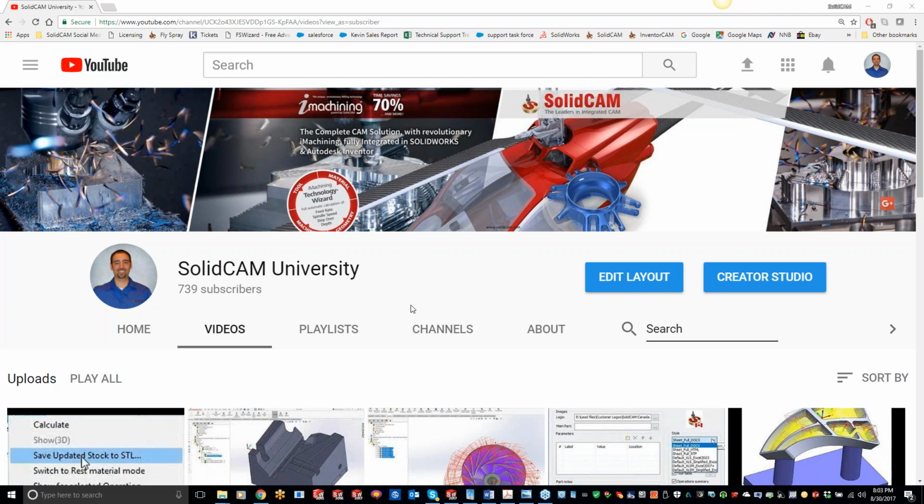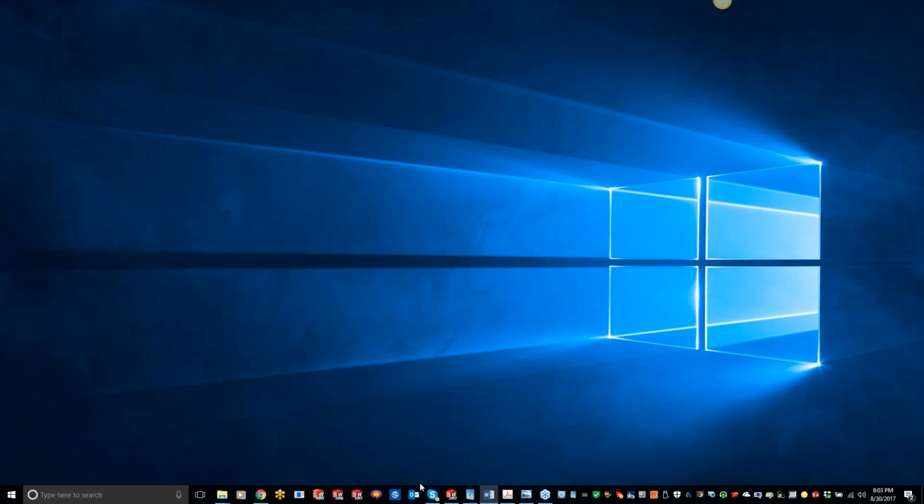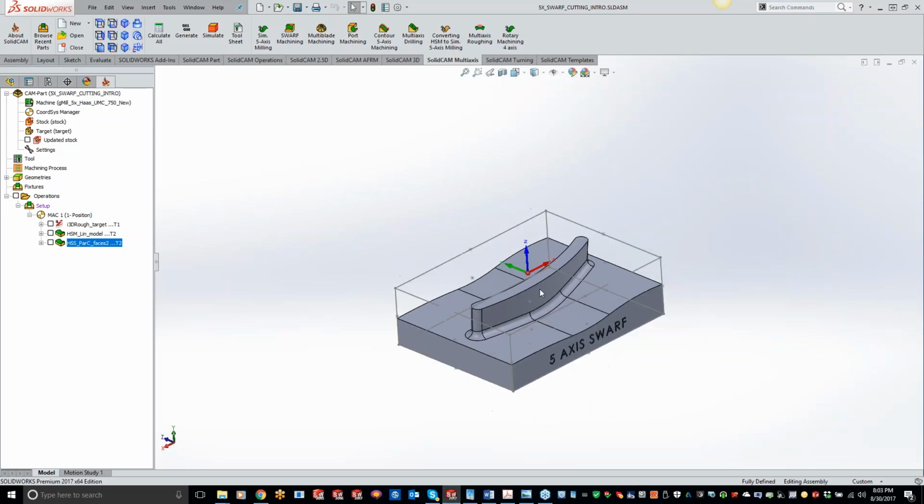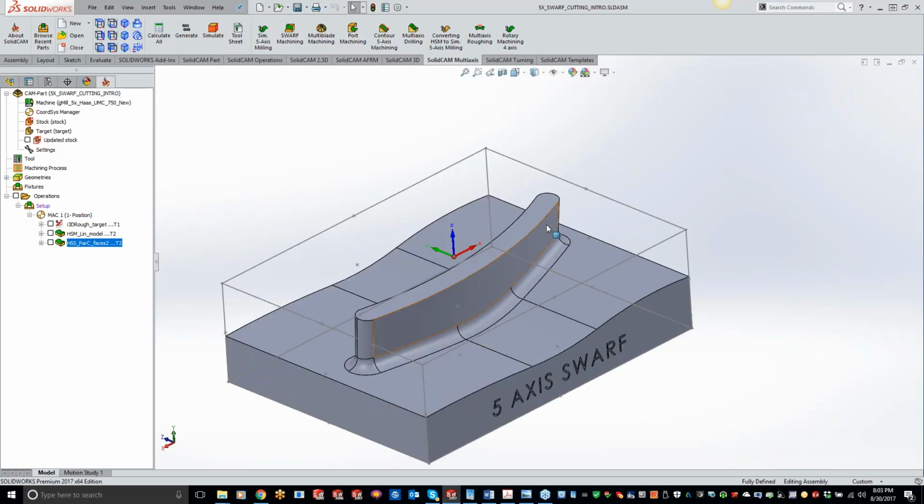So I guess with that all being said, guys, let's go ahead and get the ball rolling here. Tonight we are going to be covering 5-axis Swarf. With the Swarf, it's meant for sidewall axial relief feeding. It's one of the simultaneous 5-axis milling operations, and it produces a really good target surface with only one cut, utilizing the full flute.